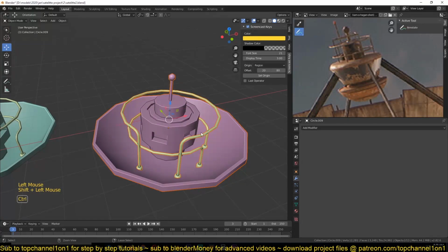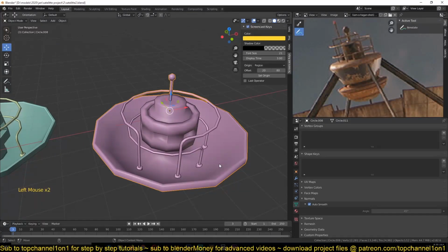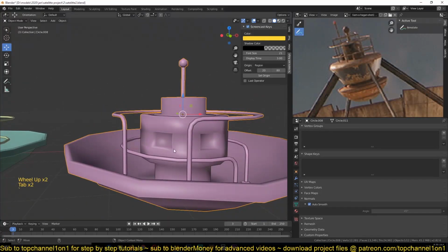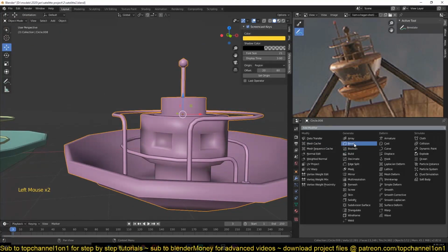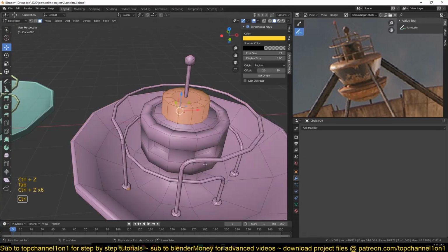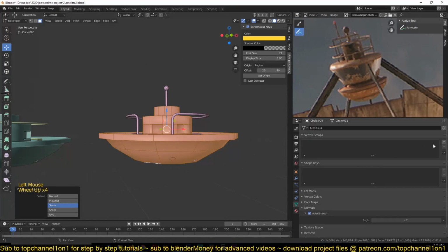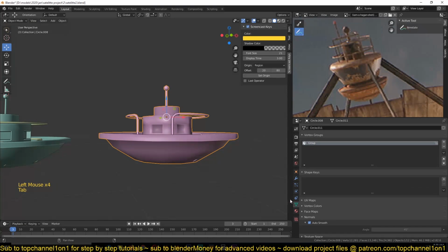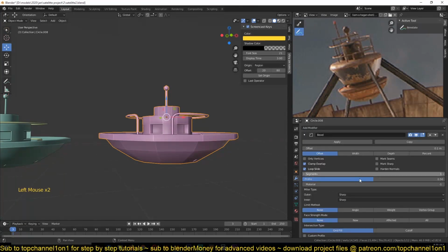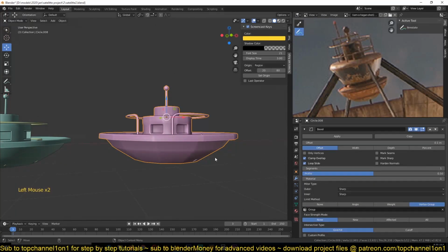So join this to this, and make sure we use auto smooth, which is breaking the smoothness here. Let's just bring back the bevel, and what we can do is apply the bevel only to this object here. Actually no, we don't need to undo, so I can select this, Ctrl L, so that I have the entire thing selected, and go to vertex group, assign a vertex group, and add the bevel back, but make sure that it's only set to this vertex group.